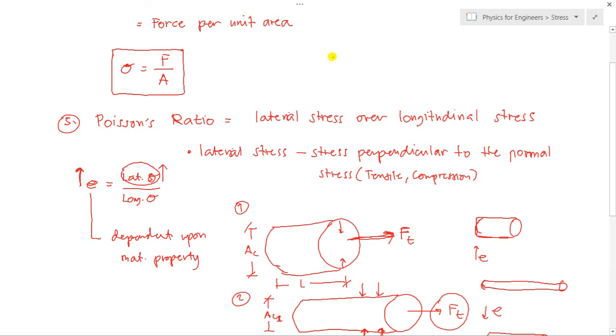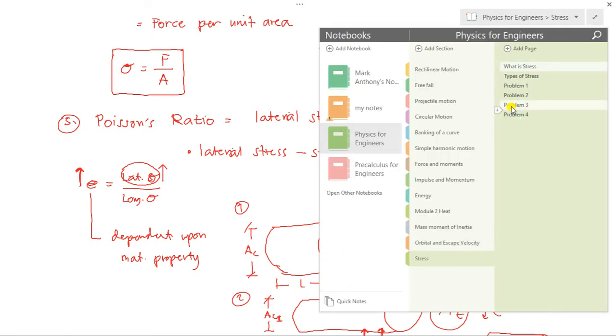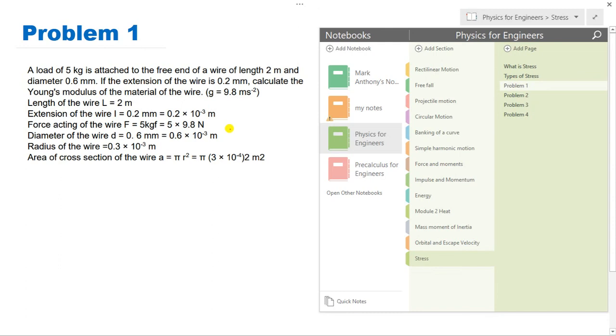Why? Because, di ba, again, modulus of elasticity E is equal to the stress over the strain. So kung dako kini, gamay ang imong strain. And then strain is associated with deformation. So meaning dili elastic ang imong material, gahi kini. Now if you have a small value for your modulus of elasticity, meaning your material possesses a considerable amount of deformation, therefore that is elastic, given that our normal stress is constant. Okay, so kung walay pangutana, then let's proceed to problem number 1.